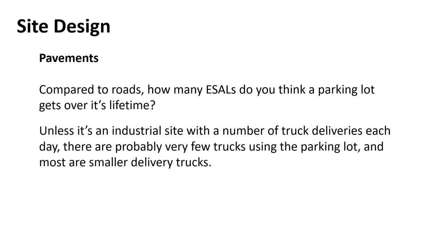Think about how many ESALs you think a parking lot gets in its lifetime versus a road, right? Even a busier parking lot is going to have a lot less traffic than a road has, and it's quite often very few trucks in a parking lot. So with your medical office building, you're going to get an occasional truck come through there for a delivery, and it's probably going to be a smaller one. Okay, yeah, lots of UPS trucks and FedEx and Amazon, but probably no WB-67s coming through there.